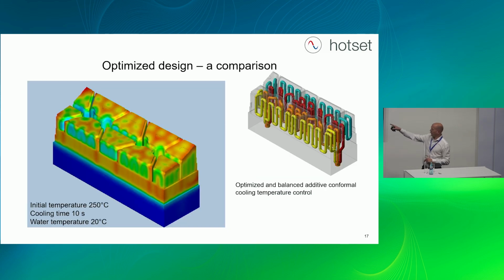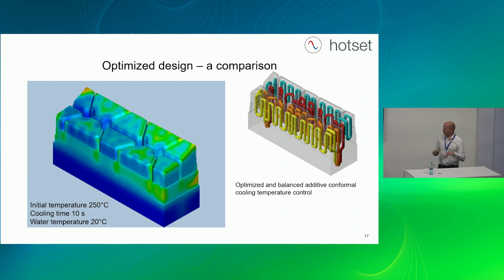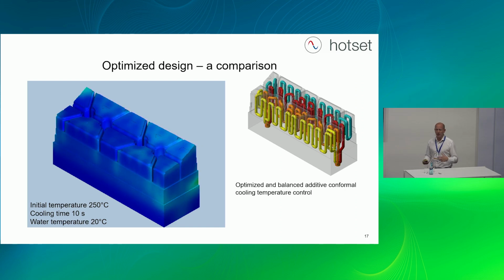You see the fingerprints, but it becomes homogeneous very quickly because the heat transfer is much higher, as in the examples before. The cooling circuits are balanced to each other and to the cavity, and we are running a lot of heat exchanger surface inside of this insert.